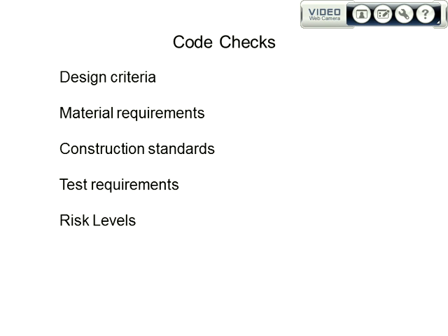I'm not expecting any risk analysis at all here. The main risks that are controlled in a major accident hazard pipeline, which we discussed at the safety lecture, are the routing of the pipeline and the distance from occupied buildings. So you've got to look at the proximity distance that is in place for the pipeline at the moment.